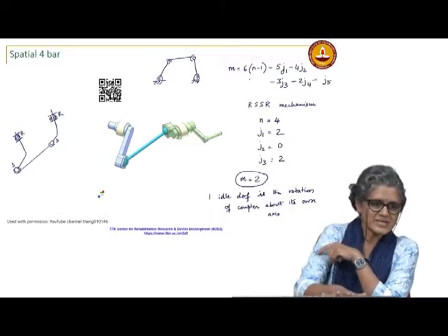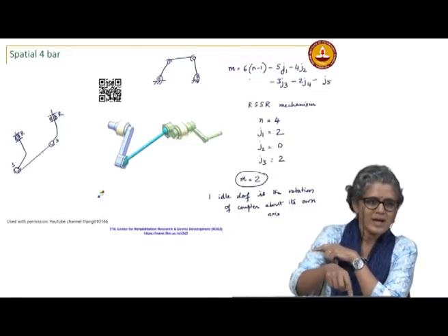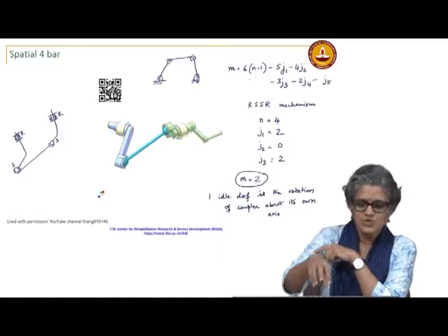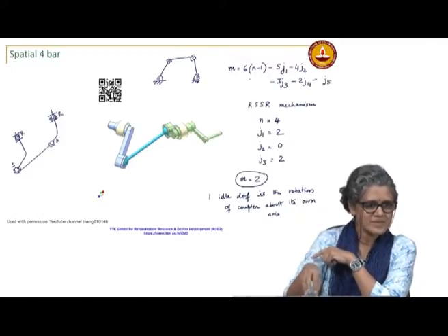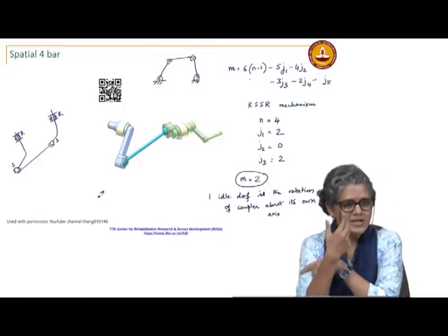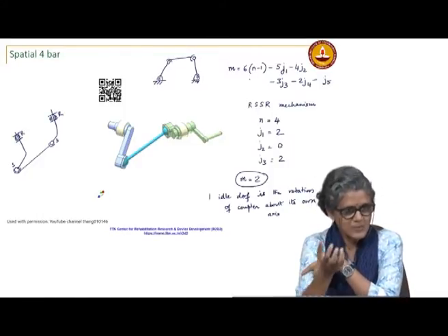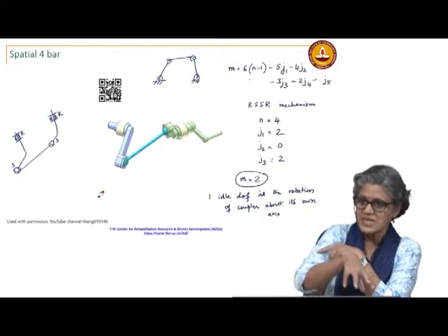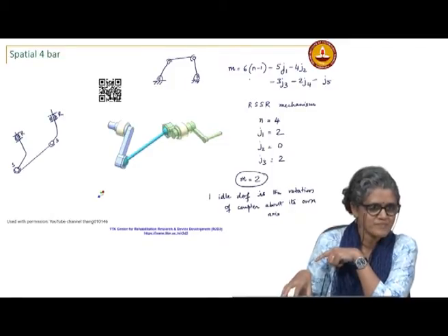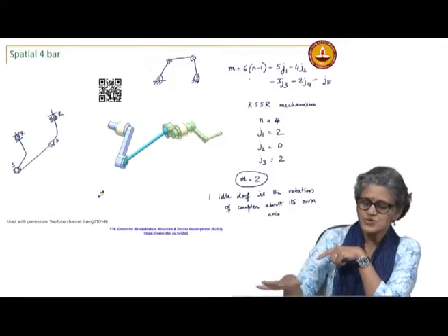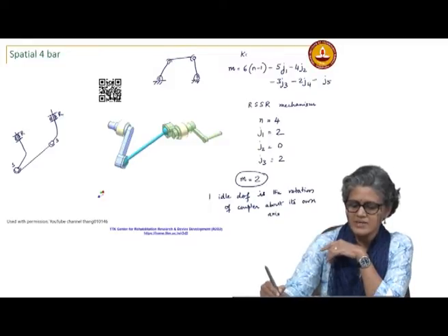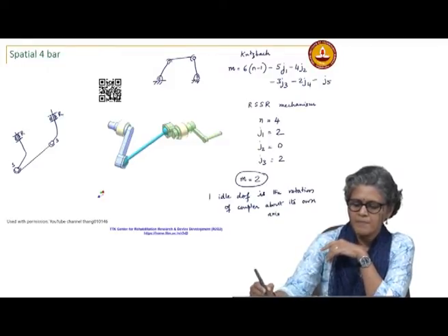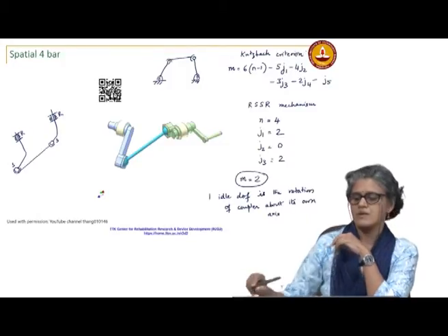That is because when I restrict it to the plane, I have already said that is my axis. So, the other 3 joints, when you apply this equation, they are also taking away 1, whereas they are not independent, right. It is the same constraint applied to all 4 joints when you restrict it to the plane. So, you do not apply this criterion, the spatial mobility criterion, to a planar mechanism. Good question.